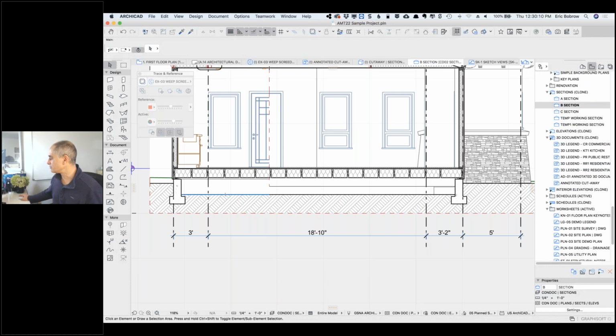When copying a plan with the marquee, the annotations within the section elevations do not come forward with the project. Okay, I'll have to see what you're referring to. Yeah, that's right. When you're copying the virtual building from one project to another, it'll bring in all the stories and the annotations there, but not the annotations on the sections and elevations. That's why in the early to mid stages, when you haven't done any annotations or just a little bit, it's pretty easy. But if you've done a lot of work on your sections and elevations, then it just becomes more work to transfer it, to migrate it into the template.